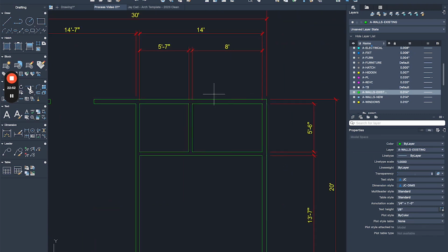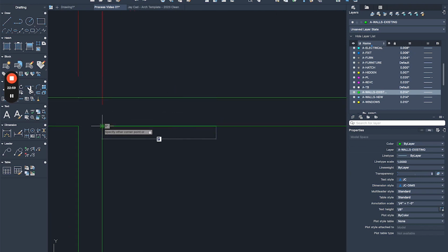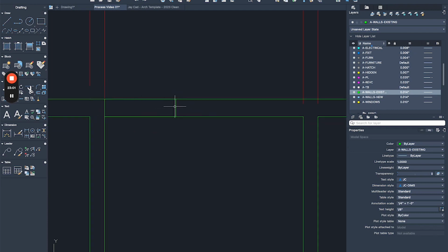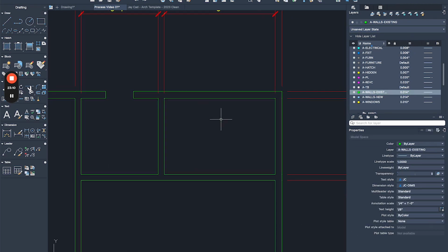I'm gonna get there. And then here I'm gonna add another window. So I can do this differently. I'll use rectangle. I'll do 2 feet away from that point, and then reference up. Then I'm gonna select it, move it, and then just move it like this. This is another way of doing things. Again, trim, join, same process literally.